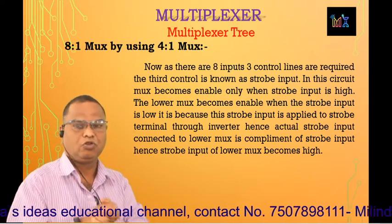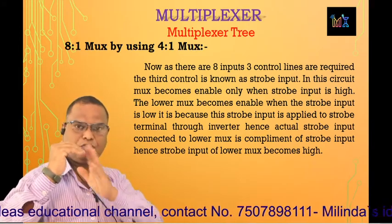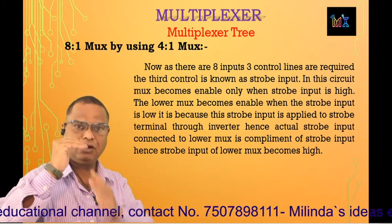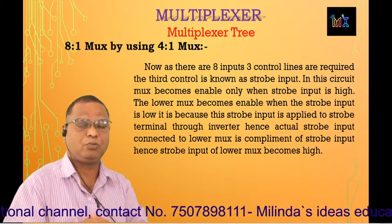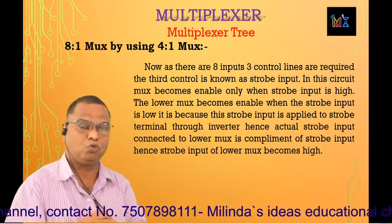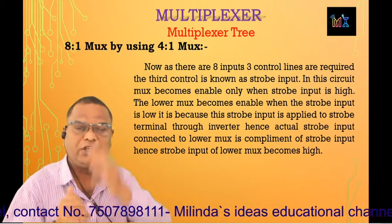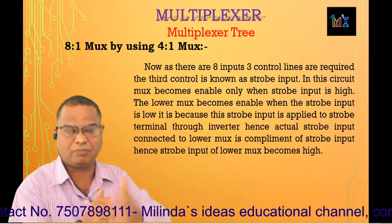So now, as per the remaining control inputs, that is 1 0 0, 1 0 1, 1 1 0, 1 1 1, the data connected to I0 to I3 of the upper mux, that is M2, that is basically data inputs D4 to D7, is selected and connected to the output terminal of that mux.